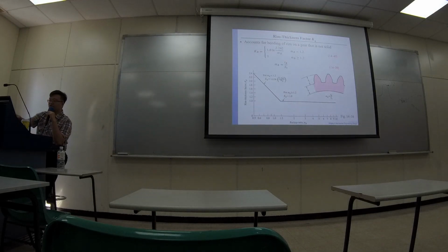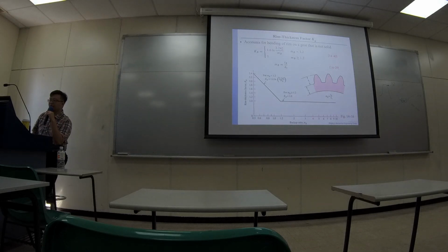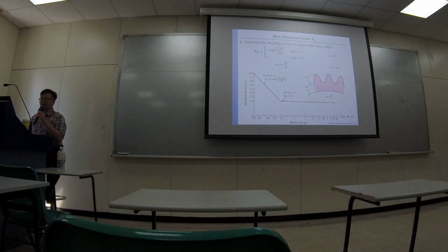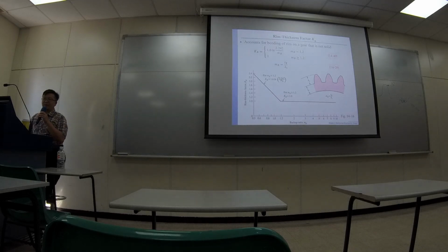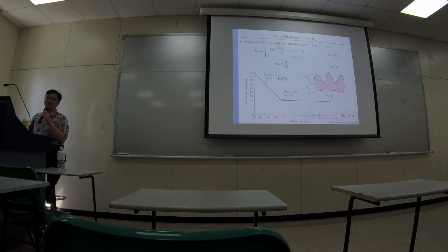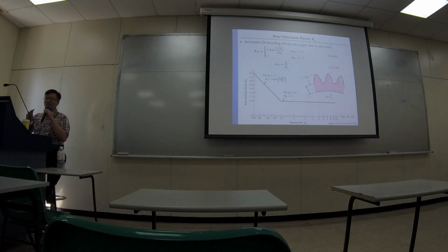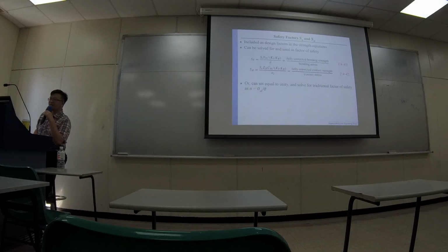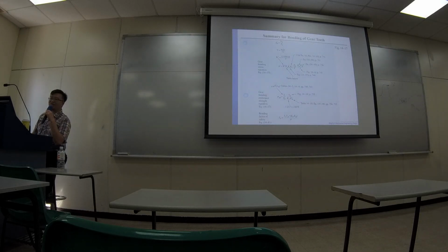Okay, and also you sometimes have gears with the so-called ring design. It's like a ring. So this part is called the rim. If the thickness of the rim is too small, it will affect how strong the entire gear is. You know, the entire rim will be bending a little bit. And also the safety factor right here. Combining all these, you have equations like that.